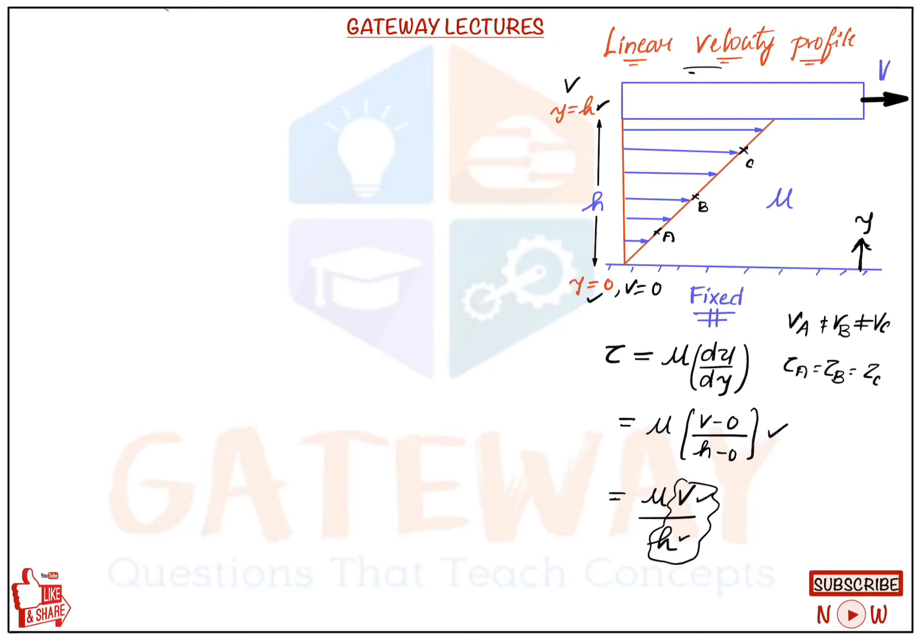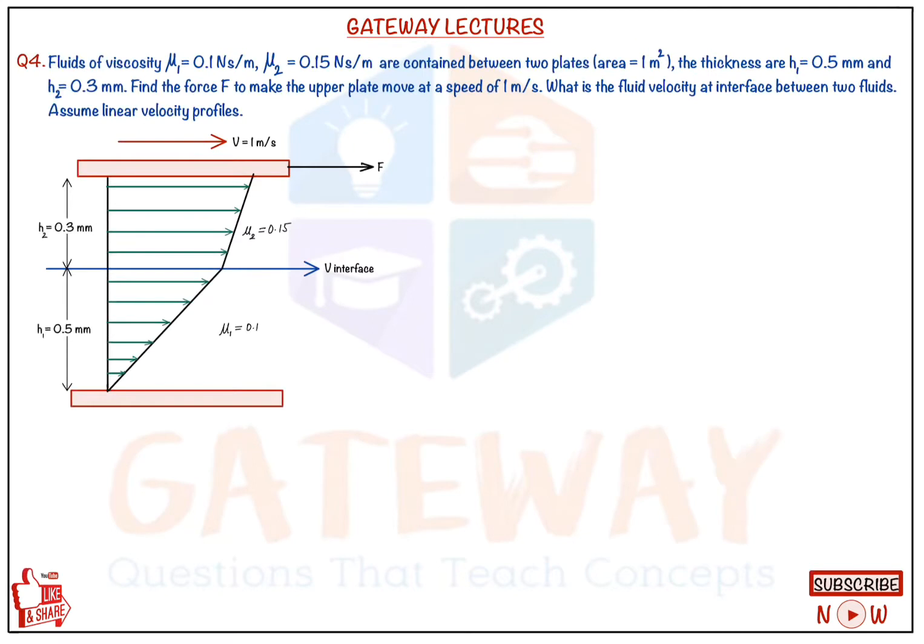This is the only basic concept required to solve the question. So let's go through the question. For a linear velocity profile, we know tau is equal to constant. Just now we've learned the basics. So let us consider the interface layer initially. First we'll calculate the velocity of the interface layer, then we'll calculate the force required. This is the interface layer, and on the interface layer it is having some velocity vi.